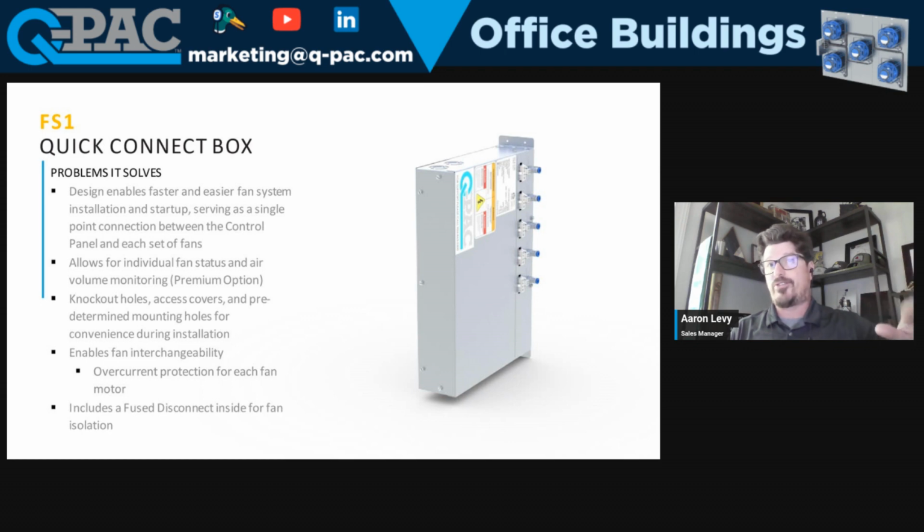There's a fuse disconnect circuit breaker inside there with mini fuses in there. That tends to be the biggest point of failure in there. That's what it's designed to do, to catch anything before it gets to the fans. So typically, if you do get a fan alarm, normally what I tell people is to check the fuses inside that disconnect as the first step. Normally we'll ship some fuses along with it, because it's very common if you get a high voltage spike or some kind of load change, maybe dirty power, that can take those fuses out relatively easy. But that's what it's designed to do. It's easier to replace a $5 fuse than a multiple $1,000 fan.